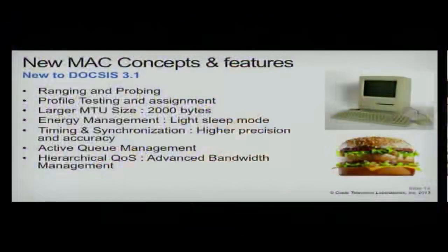The idea is the CMTS would send down a command to the modem, and on the downstream, the CMTS would be sending down test code words, and the modems will report back metrics saying, hey, I could decode so many code words, this is my bit error rate, this is my MER, and report that back to the CMTS.